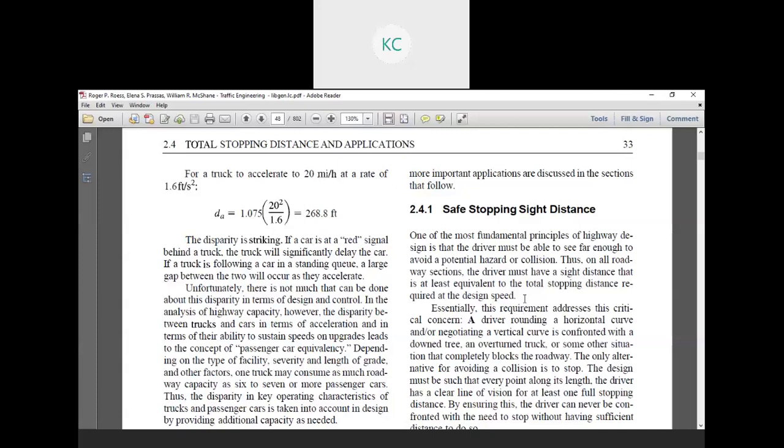When we talk about the national highway, the design speed for a passenger car is 100 kilometers per hour, and for a truck it is 80 kilometers per hour. This kind of speed regulation, speed signage, or the facility of speed studies is known as design speed. Different classifications of roadways or highways have different design speeds.